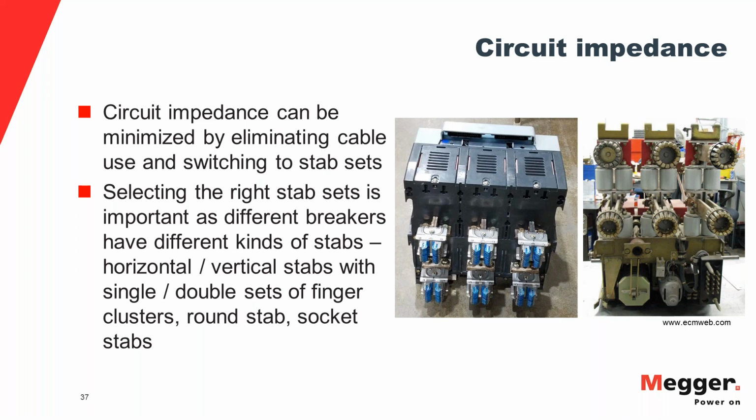They have all sorts of stab sets. They can have vertical stabs, they can have horizontal stabs. The stabs can have a single set of finger clusters, or double sets of finger clusters. They can be round stabs or socket stabs. So having the right stab set for the range of breakers that you have can be a bit of a problem.